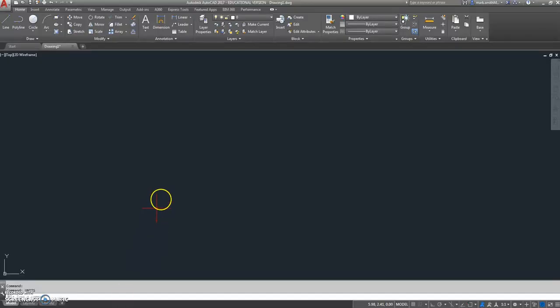So go back to AutoCAD. I'm going to type in limits, and the lower, I typed it wrong, limits. Lower left corner is 0, 0, and notice inside the chevrons is a 0, 0. Notice that it's showing 2 decimal place precision because that's what we set it to. So we'll hit enter because anything inside the chevrons is what it will do if we hit enter. Now it's asking for the upper right. Notice inside the chevrons is 12, 9. We don't want that.